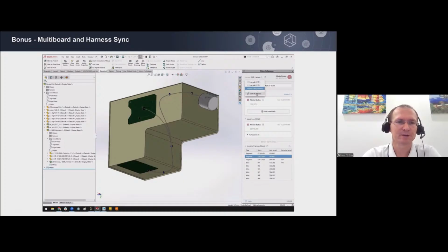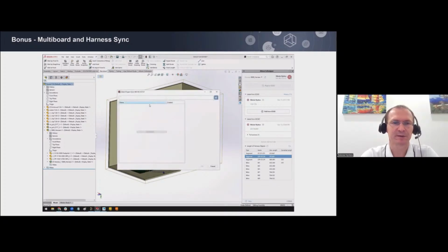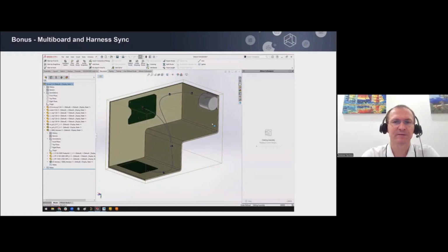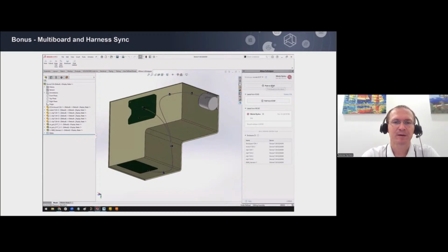So the mechanical engineer now links, or establishes the linkage between, the device assembly in MCAD and the corresponding multi-board project with the multi-board schematic diagram. We see it. And after the linkage, this design, this assembly with the parts of enclosure specified for the synchronization, is being transferred from MCAD to ECAD.